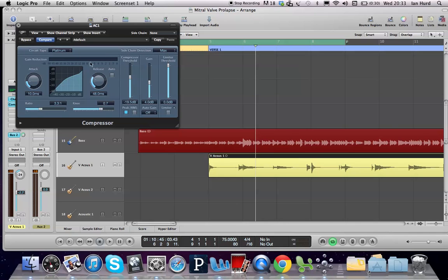We're getting gain reduction up here every time it goes above the threshold of minus 19.5 dB. So, you know, without this gain, it would be a lot lower. If we set that to 0 dB, i.e. no gain, then it would sound a lot quieter than it would do with the effect bypassed. Okay, so we want to add in a little bit of gain to make up for that gain reduction.